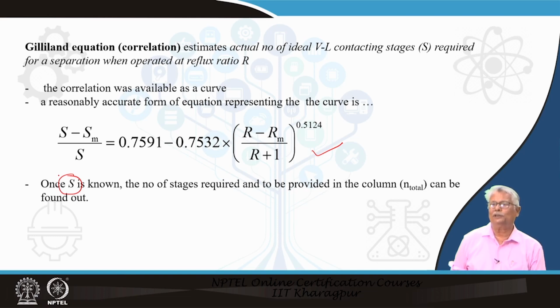From this we know we will be subtracting and adding 1 for different reasons, for the reboiler, condenser, partial condenser, taking credit for feed tray or not, and we definitely will be knowing the number of trays required in total for the desired separation within the column itself.